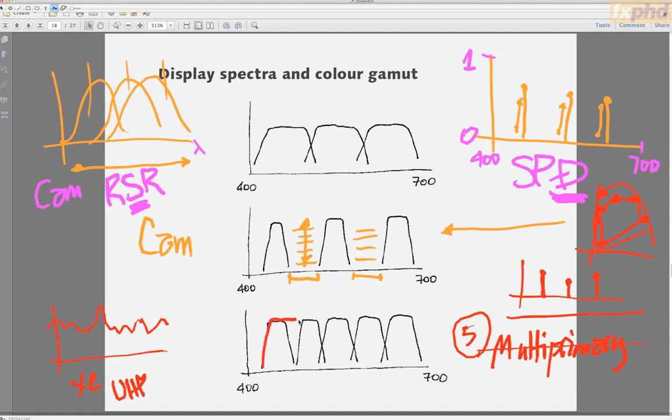Another example I can give you here is Sharp, which basically produced direct view LCD screens with 4 primaries. They call it Quadtron. And it's got a yellow primary. So the Sharp example is one idea of a multi-primary system with a 4th primary. Honestly, they picked the wrong primary, though, because it really doesn't improve the gamut compared to what you can get with classic RGB LCD. It does, however, lead to brighter pictures. There is an efficiency gain in taking the Sharp approach.